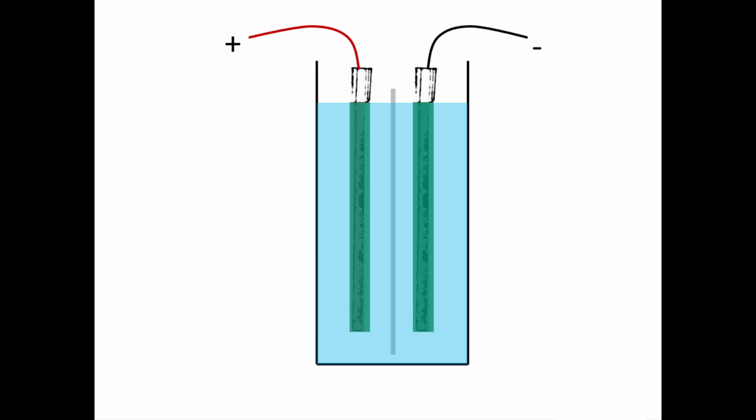Now, as far as vibration goes, if a battery is not secured properly to the vehicle, and let's say the battery was discharged and recharged, so the plates were heavily sulfated, which will cause them to corrode and become more brittle, you can have plate deterioration, which is normal over the course of the life of the battery. In this example, you're going to see the plate break apart. It's going to start to break and fall to the bottom of the case, and this plate debris can inadvertently touch and then short out the cell.